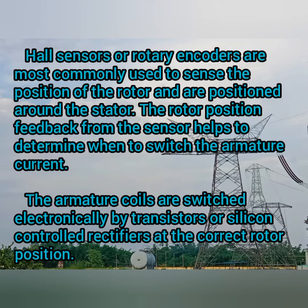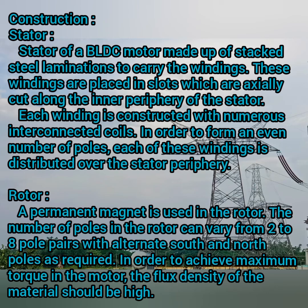Then the armature coils are switched electronically by a transistor or a silicon controlled rectifier or thyristor at the correct rotor position. Construction wise, this mainly has two parts: the stator and the rotor. The stator of the BLDC motor is made up of stacked steel laminations to carry the windings.